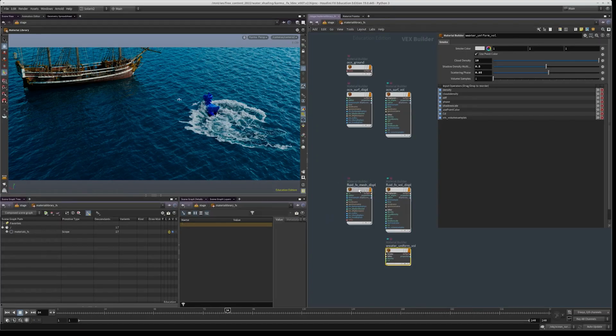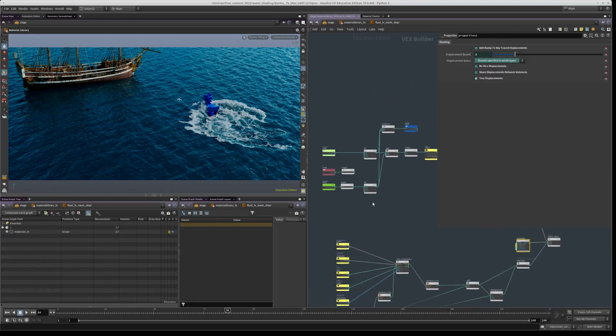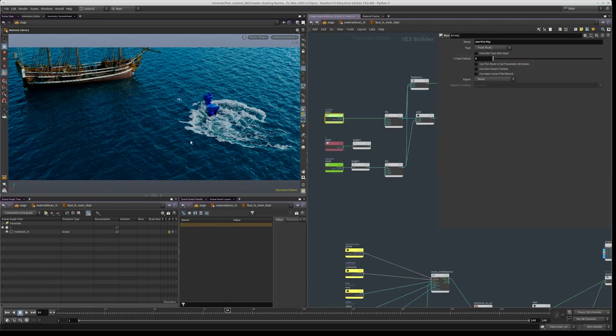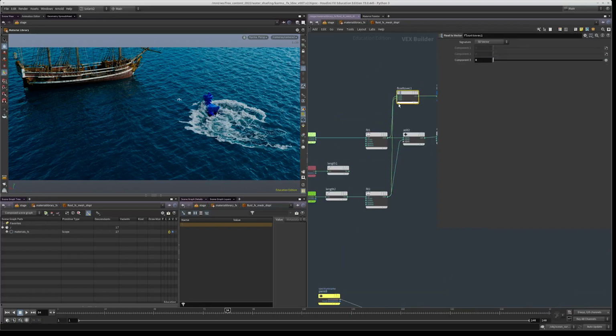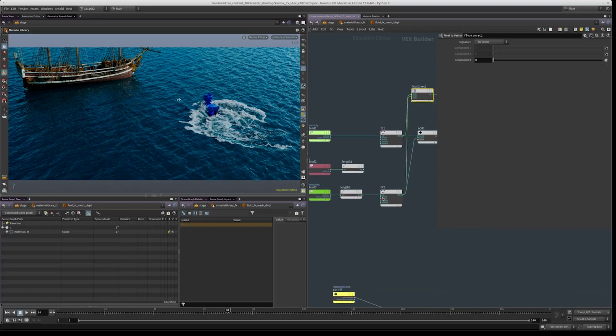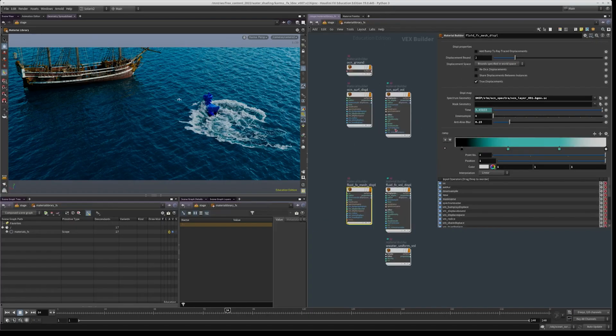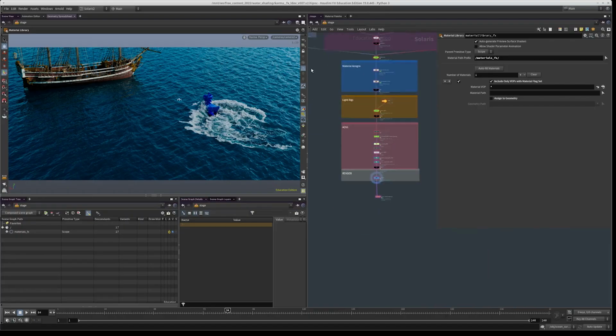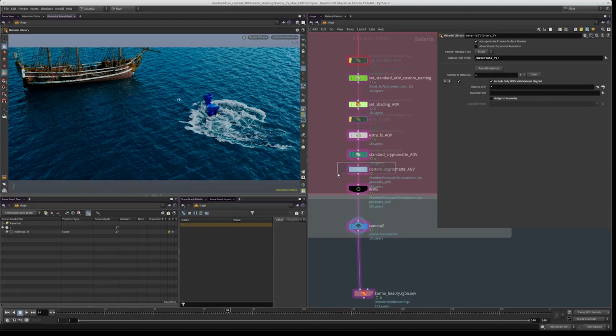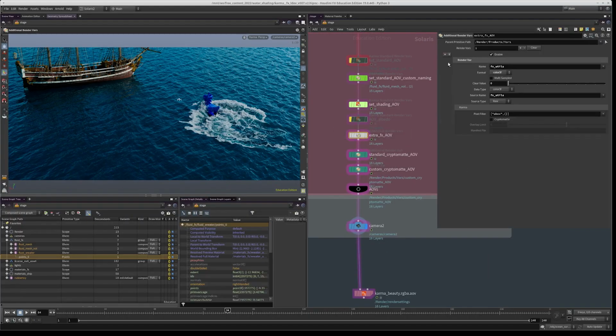And then it's the mesh, displaced mesh. So we are changing the color of the diffuse of the water using velocity and vorticity, and we simply wanted to export this data as red and green. So using a float to vector, the red is going to go to vorticity, and the blue green is going to go to velocity, and then we export this as a color called effects util. That's how we create custom AOVs, same as Mantra before, and this is how you would declare an extra AOV in Karma for them.